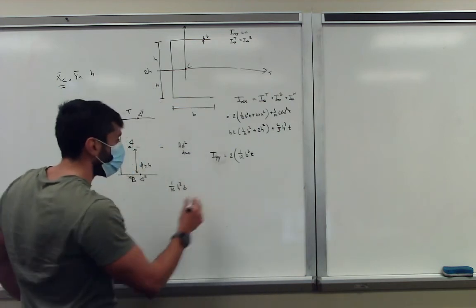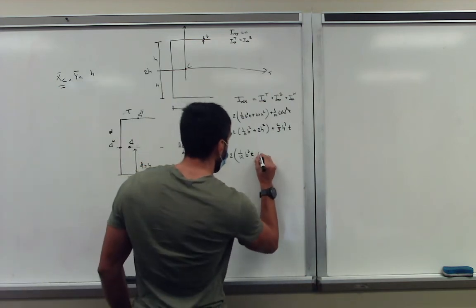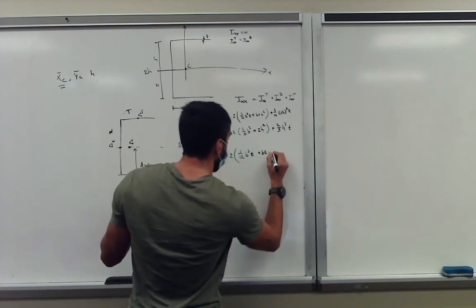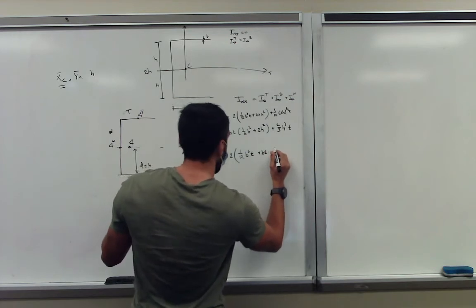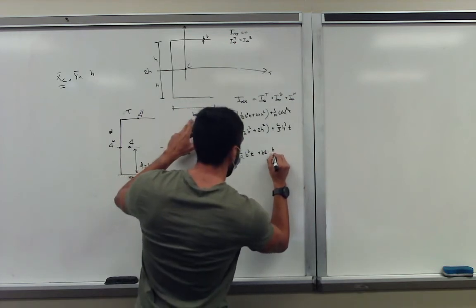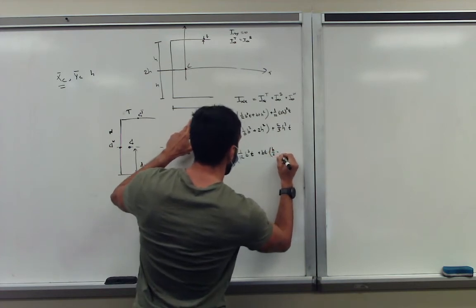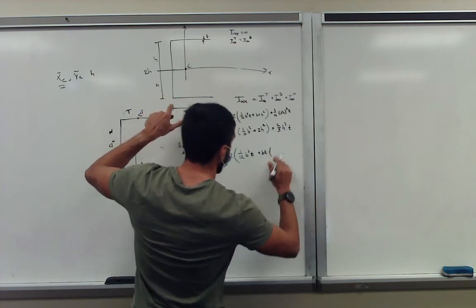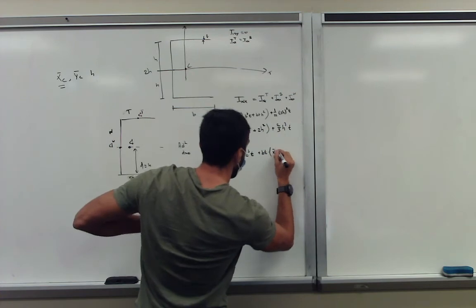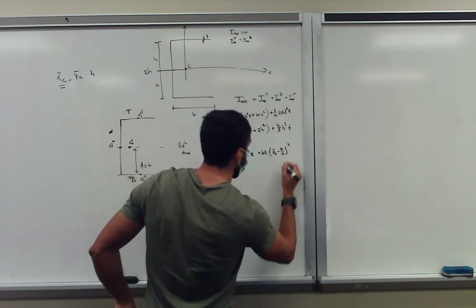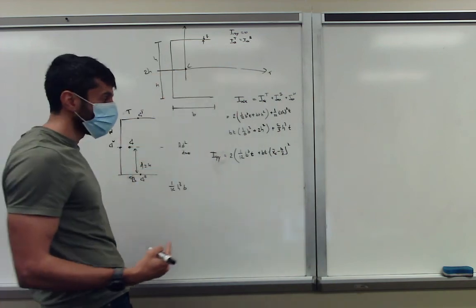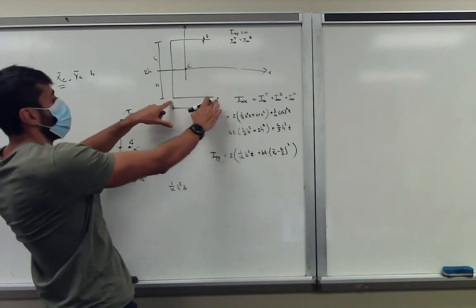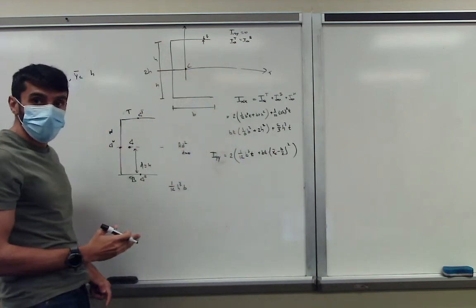So basically, in this case, we have this, and then we have to add the standard term to it. So that's b times t, multiplied by that's the area, and the distance is basically, in this case, b over 2 minus, let me see, is that correct? Now we go to the left. It doesn't actually matter. So we get xc minus b over 2 squared, because we're going to go basically to the left. That's your moment of inertia from the top and bottom, including the shift.